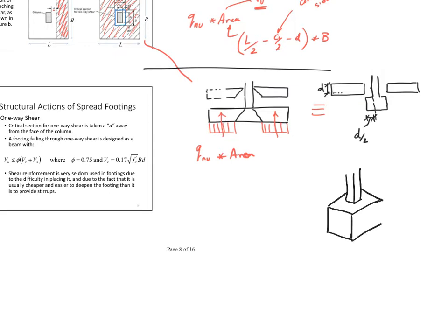I will resemble the punching to be like this. What is this? This is the part that went down with the column, and the remaining of the footing went up. Right? That surface is the surface of breaking. So it's very important to calculate it. How do I get this surface?